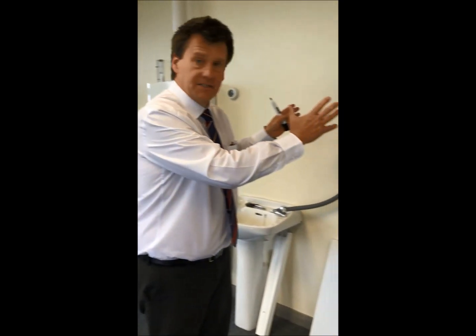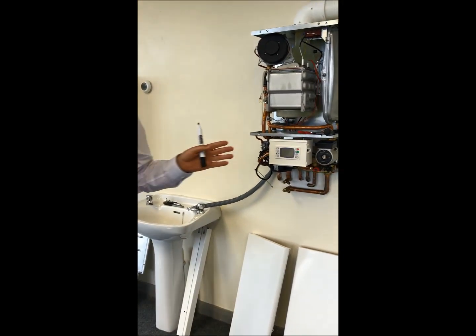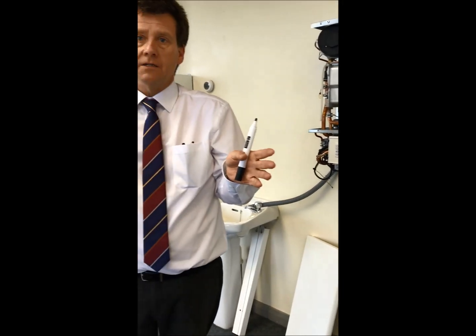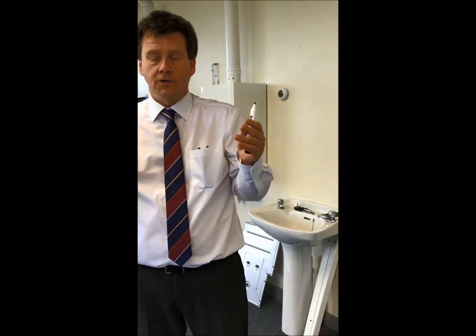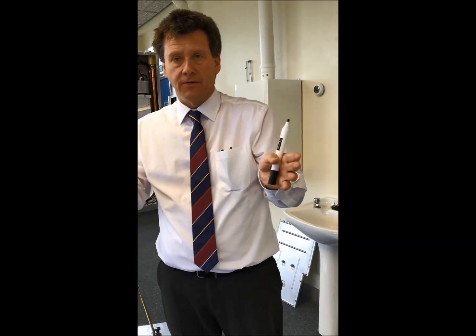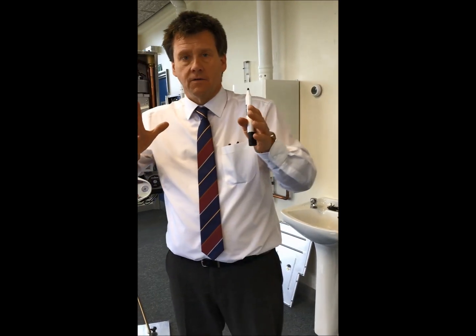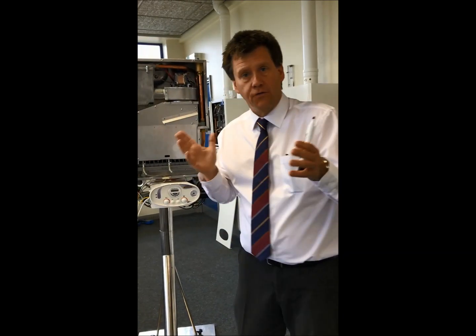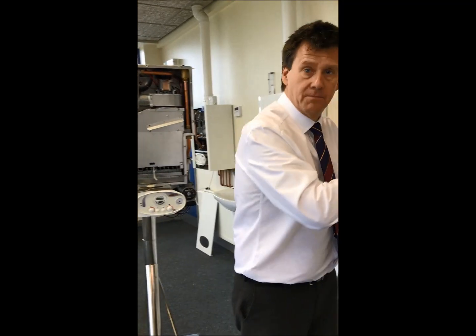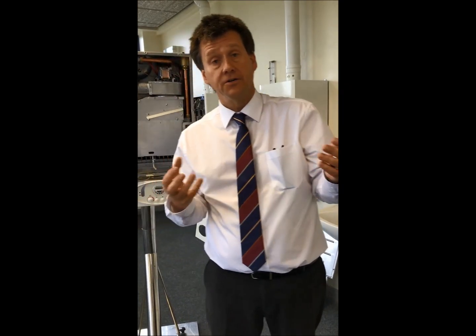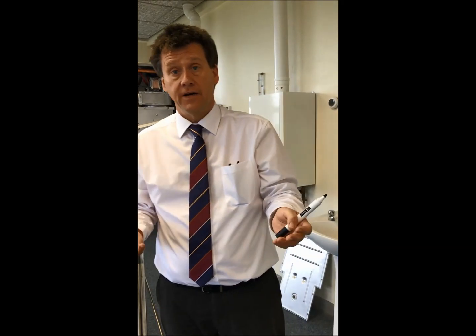Sorry guys, these fault finding codes are handy to have, but the whistles and bells, at the end of the day, you're the engineer, you're out there actually fixing it. They're a good handy guide, but train the trainer again, and let's be engineers. There's only two failures on any gas boiler, whether it be a pre-mix or an atmospheric. One of those failures is attributed to an overheat situation, and the other is attributed to flame failure.